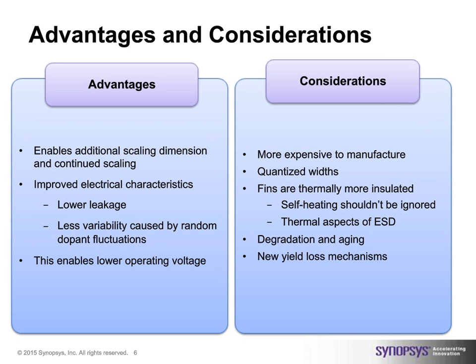And those considerations, first of all, start with making FinFET manufacturing a little bit more expensive initially. As we move forward, of course, that will probably go down, but the initial step is definitely there. Also, the width that we're playing with on the device side is quantized because you can have 1, 2, 3 fins. Every time you add a fin, it is quantized in terms of additions. So the granularity of additions is by number of fins.